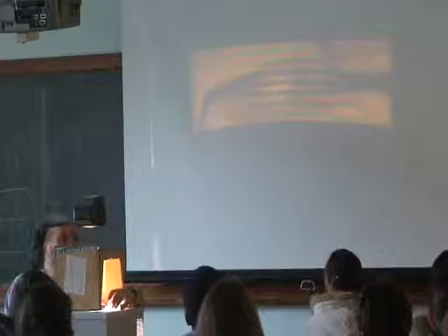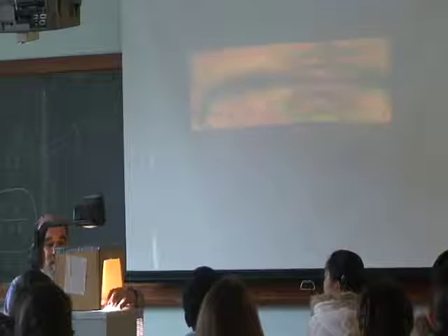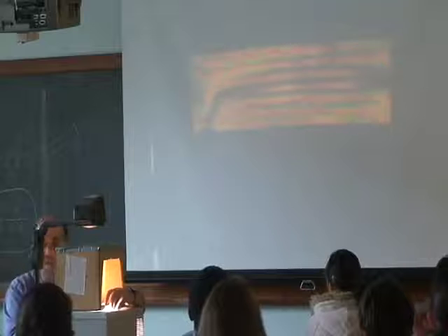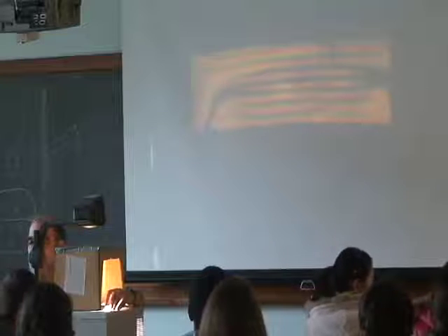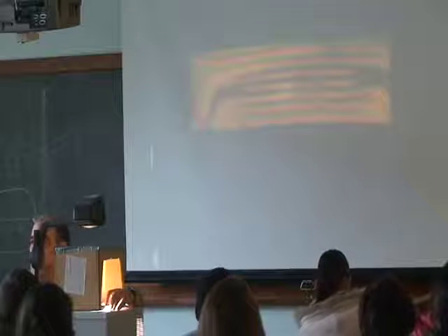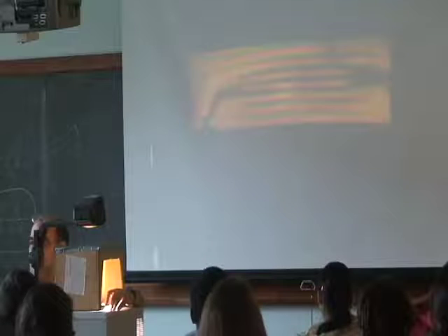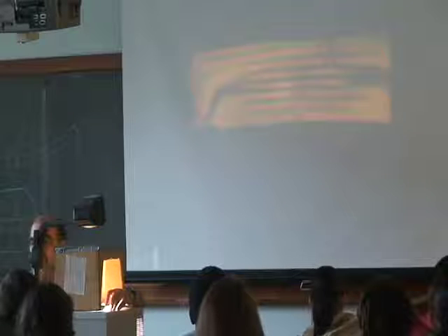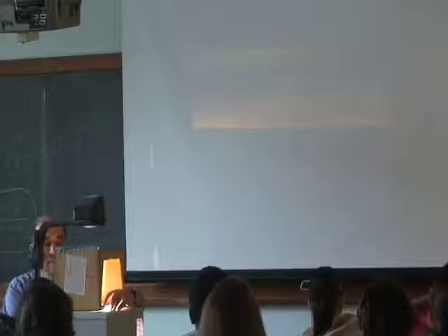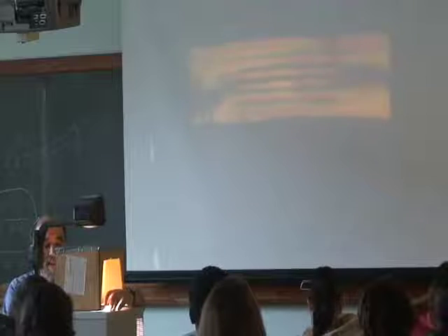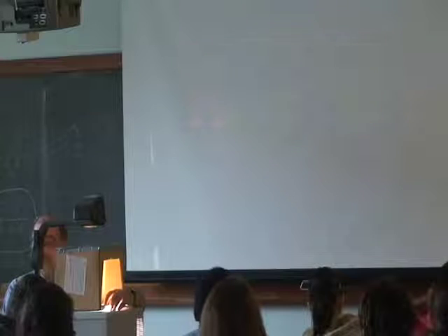What do those lines mean? Those are lines of constant tension. So for those of you who are taking Math 192, those are contour lines of the tension in the material as a function of position. The middle line is a line where the tension is 0. The lines at the top are where the tension is high. The lines at the bottom, tension is low. And these lines of constant tension are more or less parallel to this beam, the way I'm loading it here with 2 couples at the end.